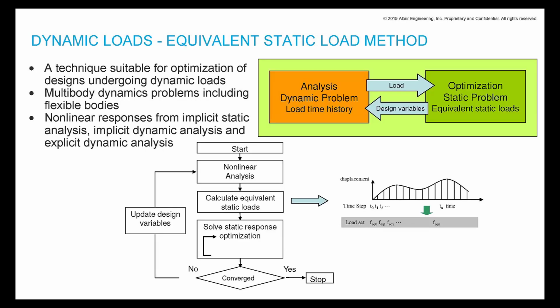Equivalent static load method is an optimization technique for designs undergoing dynamic loads such as multi-body dynamics problems, including flexible bodies and nonlinear responses from implicit static analysis, implicit and explicit dynamic analysis.